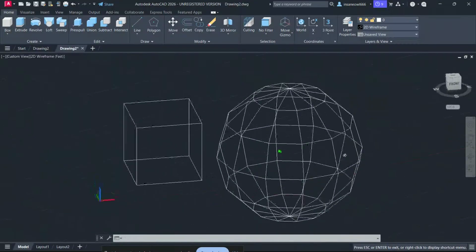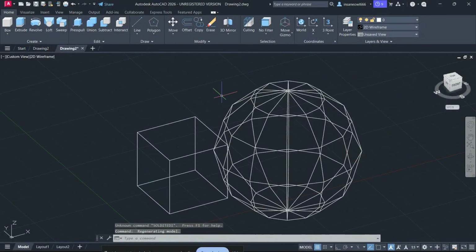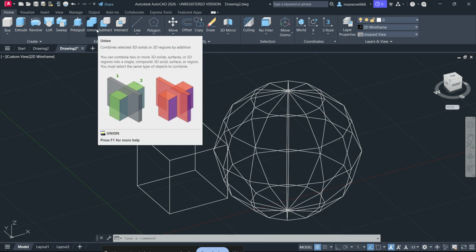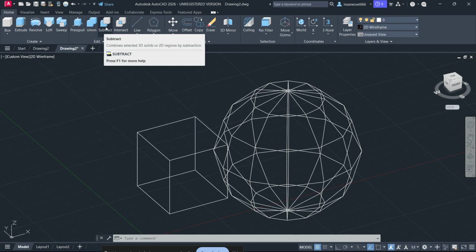If you're seeing AutoCAD error code 18050, don't worry. This usually points to a modeling operation error, specifically a Boolean intersection failure. In simple terms, AutoCAD is having trouble figuring out how two 3D solids should combine, subtract, or intersect. That means the shapes may be touching in a way that confuses the software, the geometry may be too complex, or the solid itself may be slightly corrupted.